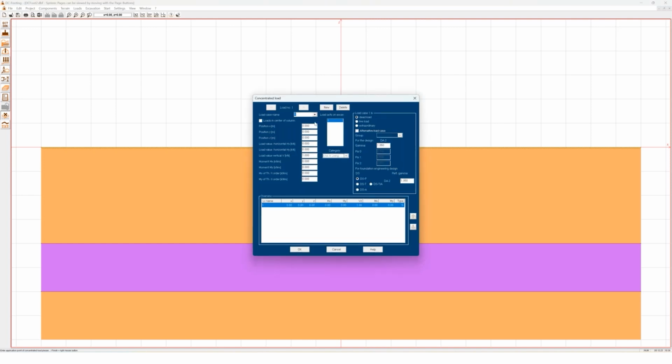And you can add different load cases with vertical, horizontal loads, from different directions, and bending moments. And there's the opportunity to enter bending moments from the theory of second order over here. And then we have a first load case, which is a dead load. And we have a vertical load of 300 kilonewton.